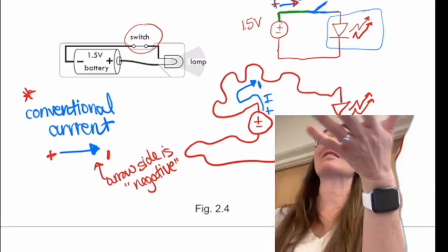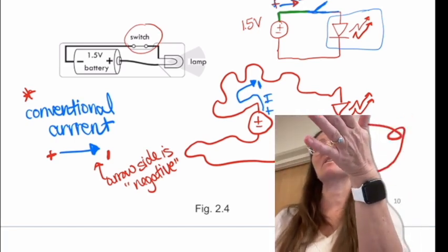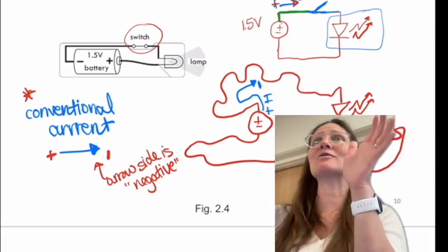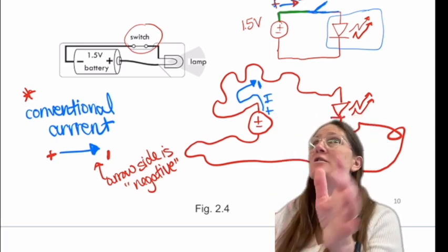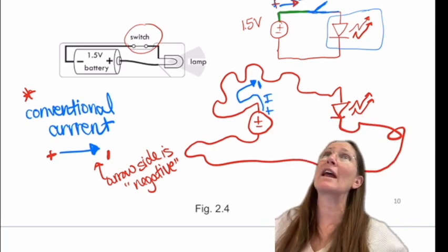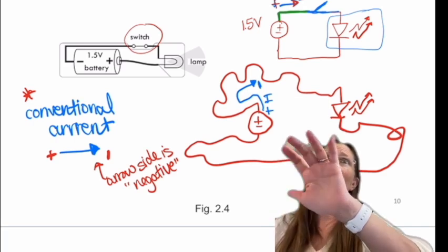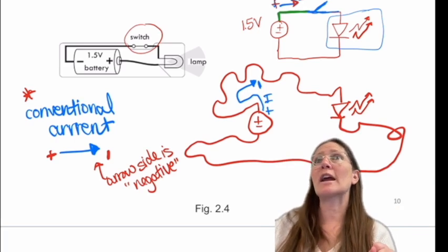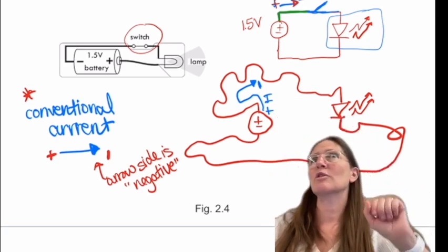They're going to give you the mechanical information from it. And yes, well, I guess I should say that back. So yes, the length will determine some capacitance or resistance or inductance. What we call that is a parasitic effect. And so when we design or we're analyzing, we usually ignore those parasitic effects and let a simulator usually tell us more information about that. So on a hand-drawn schematic, we would ignore those issues.